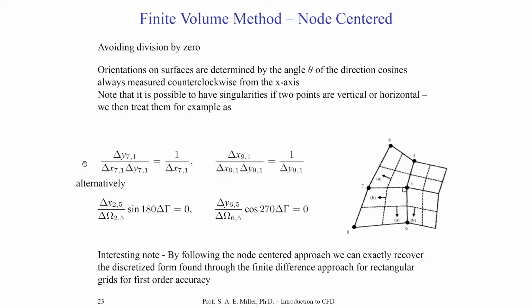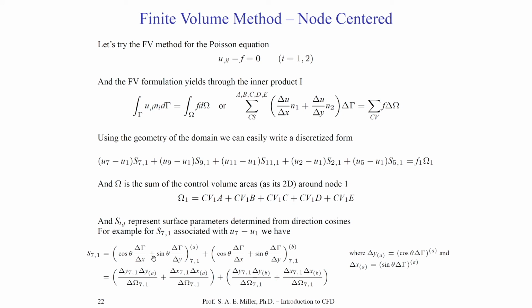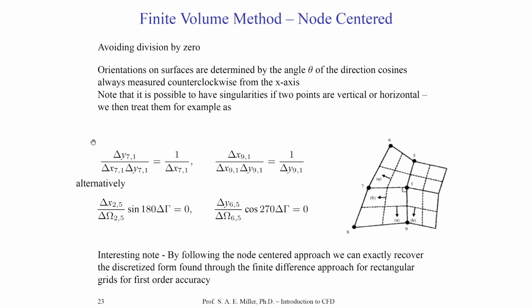After you write them down, you would of course have to go to the boundaries and set the fluxes to 0 if, for example, there's no flux, or specify a flux on the boundaries of the domain for each particular volume if you would want to enforce like a Neumann or inflow boundary condition. Now you can see there's one downside of this approach, and you would have to correct it algorithmically through detection, that is, if statements within computer code itself. For example, some of these directional cosine operations shown down here could result in major problems like divisions by 0 or 0 divided by 0.